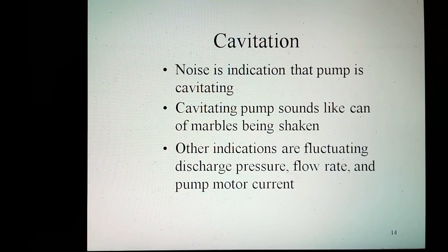Noise is one of the indications that a centrifugal pump is cavitating. A cavitating pump can sound like a can of marbles being shaken. Other indications that can be observed from a remote operating station are fluctuating discharge pressure, flow rate, and pump motor current.